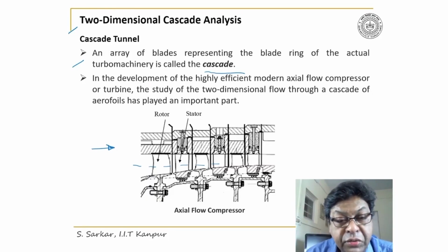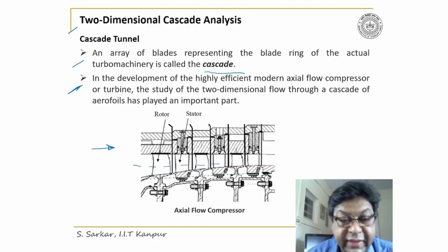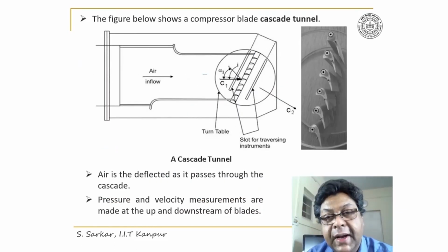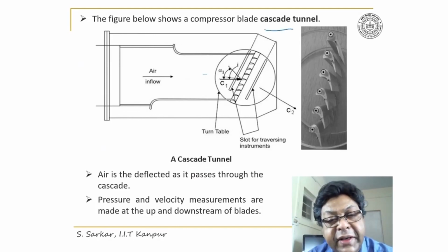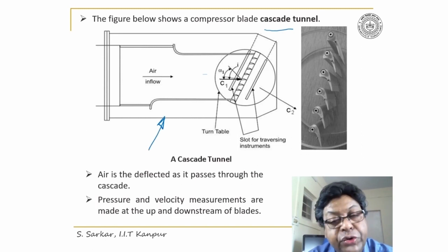I'd like to give you another piece of information: the study of two-dimensional flow through cascade played an important role in development of highly efficient modern axial flow compressor or turbine. I have discussed here the cascade tunnel. Cascade tunnel basically is a wind tunnel. So the schematic of the cascade tunnel is shown over here.